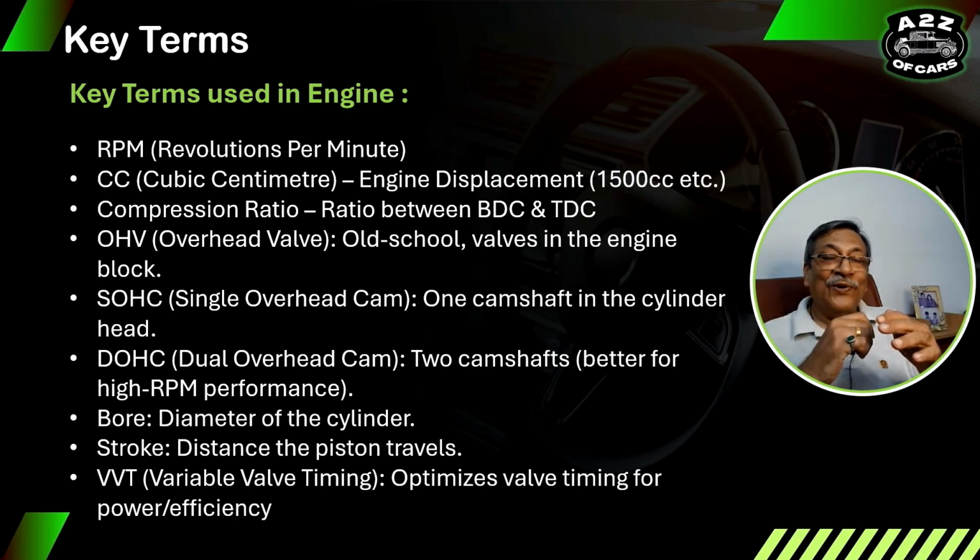If you compress more in a petrol engine, it might catch fire before the spark happens, just because of that heat. That can happen even in petrol also. So what will happen? There will be knocking, right? So all the engines are made keeping the characteristics of their fuel and various aspects in mind.